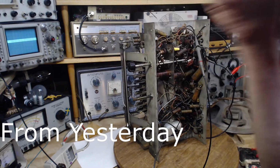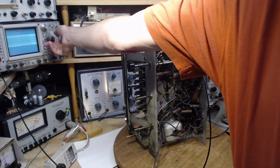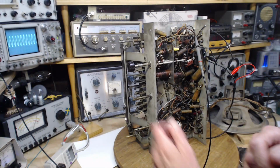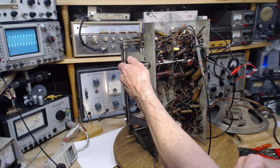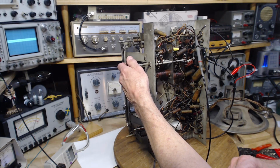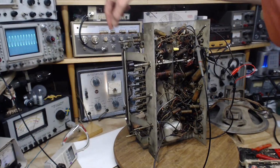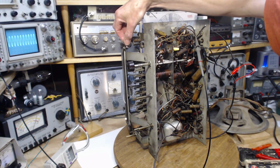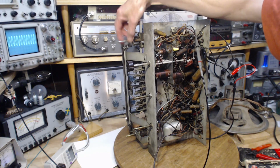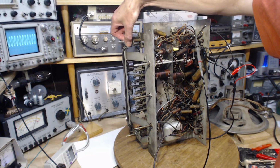So what are we seeing here exactly? Looks like the same frequency. Let me speed this up. See if we can. So there's the actual frequency. That's broadcast. See, the frequency has changed a lot. I'm going to tune the radio and see if this frequency changes here. Yes, it does. So I think what we're looking at is the local oscillator coming back out of the radio, where it's developed in the radio and working its way in the wrong direction back to the antenna. And we're seeing it here.